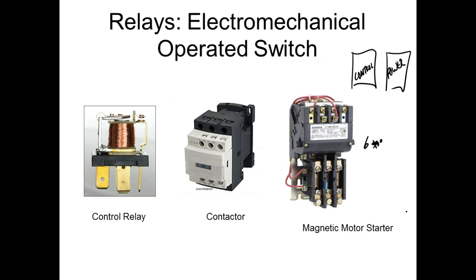So when I protect my circuit with an overcurrent protection device, it's going to have to let those motors start. So those devices are going to be rated at least at the start current, plus probably about 125% over the start current. It means if the motor doesn't start or if the motor stalls, those overcurrent protection devices are not going to do anything. They'll just sit there and let the motor just flat burn up.